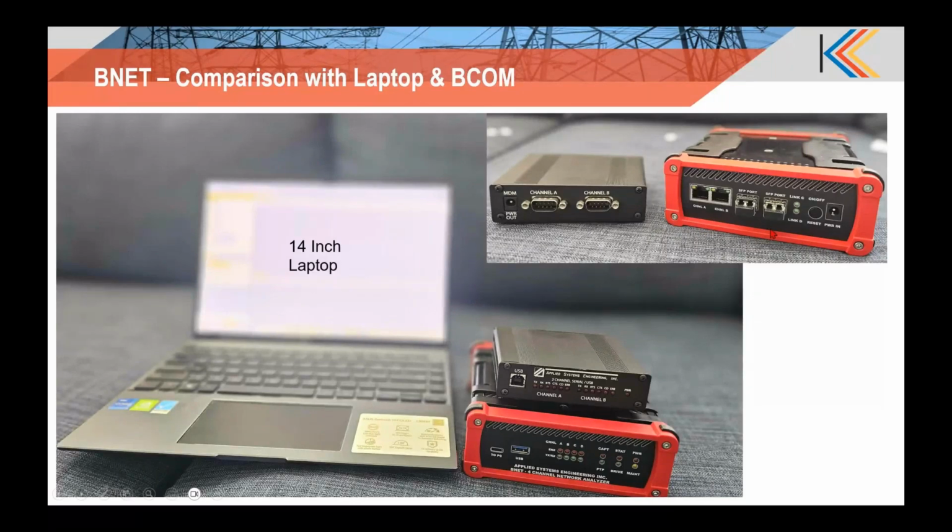So if the process bus supports fiber optic, then you will have to connect these ports to a fiber connection. Here you get the flexibility of using any of these. You can have an SFP connector with Ethernet or an SFP connector with fiber optic. By default, the unit comes with the fiber optic SFP connectors.